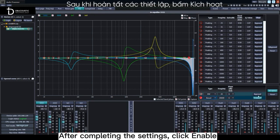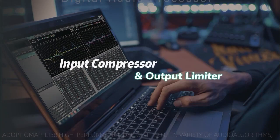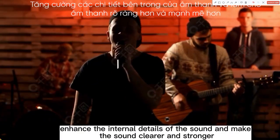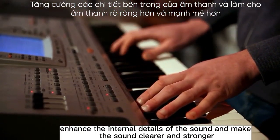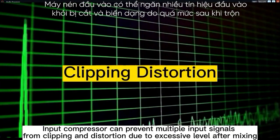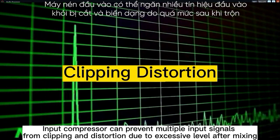After completing the settings, click Enable Input Compressor and Output Limiter. Input compression is to control the dynamic range of the sound, enhance the internal details of the sound, and make the sound clearer and stronger. Input compressor can prevent multiple input signals from clipping and distortion due to excessive level after mixing.